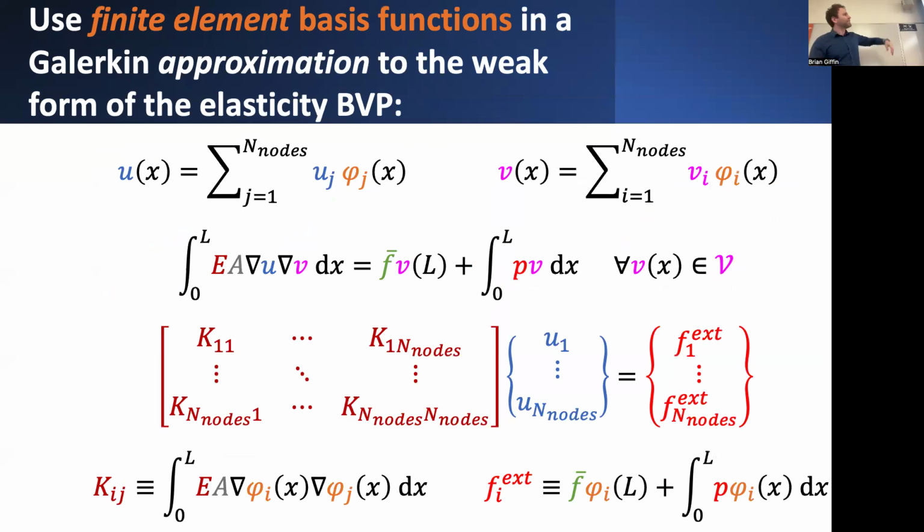So what that would look like is something where we have some candidate solution for our displacement field expressed as some linear combination of these finite element basis functions, where the unknown coefficients u sub j are just the nodal values of the displacement at these discrete nodal positions.